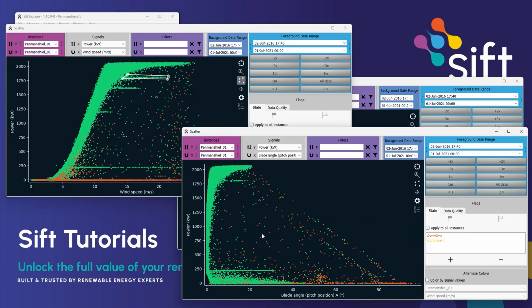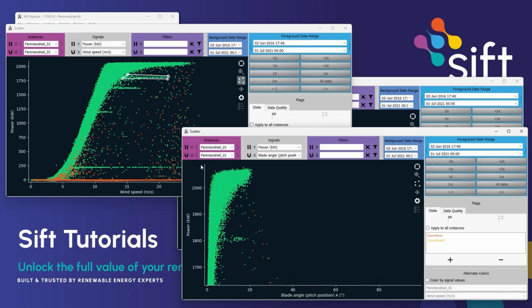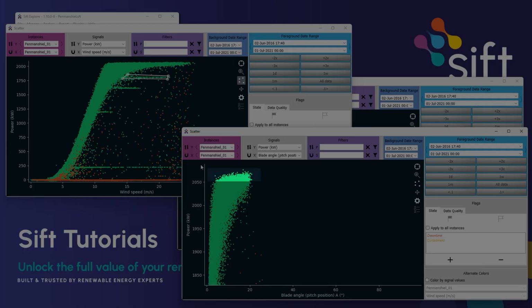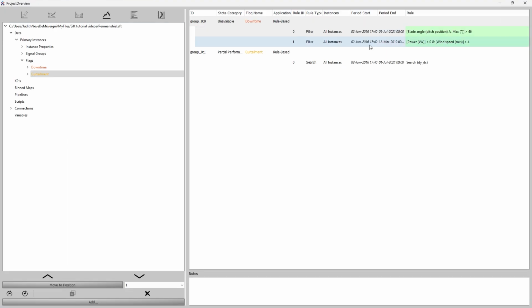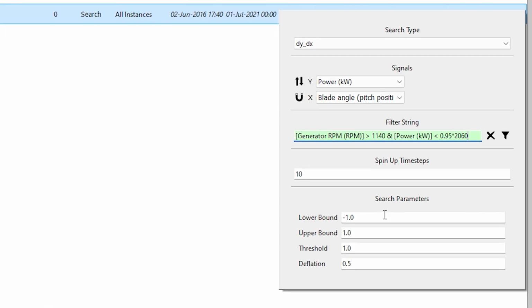Points at rated power can be excluded by filtering out points above 95% of rated power. The control strategy limiting turbine output power to rated power is the same one that is used to limit production to lower power levels. Therefore, there is no clear operational signal to differentiate curtailment and rated power control. For the analysis, this means that curtailments at levels higher than 95% of rated power will not be classified as a curtailment, but as a change in rated power.